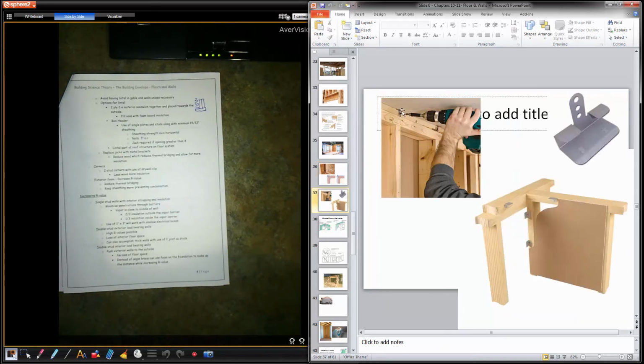You see them here being used on the ceiling. Sometimes they get used on the ceiling because you want to float the drywall to prevent truss uplift. So you can see it happening here as well, and then you have them in the corner as well. Okay. So it gets screwed onto these holes, you can see right there, and then the drywall slips into it. There's these two little teeth here. So once the drywall slips in, it has trouble coming out because it catches on these two teeth.